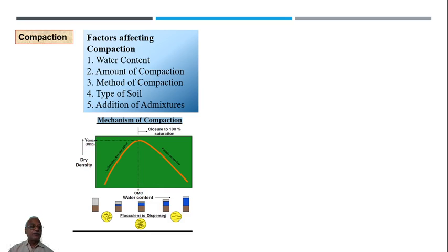If I draw the modified Proctor test diagram on the same plot, it would be something like that, indicating that the OMC has decreased and the dry density has gone up, because on this axis you are plotting dry density. So the more the compaction effort, the lesser the OMC and the higher the dry density. That is the point.